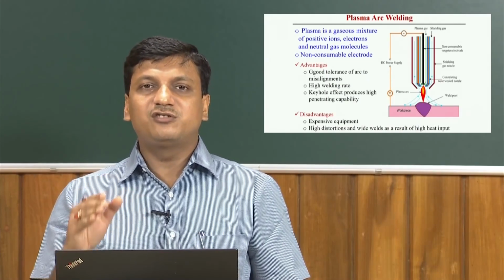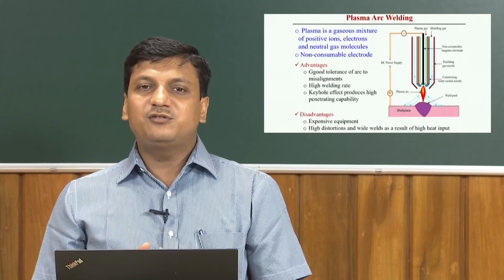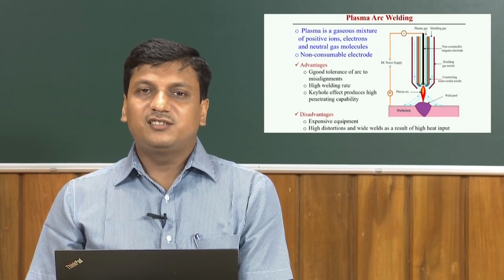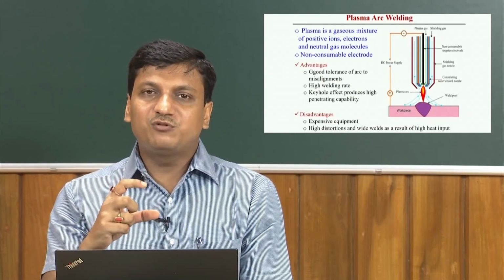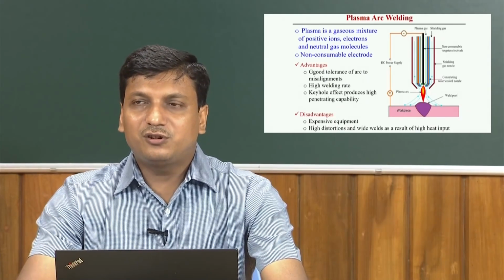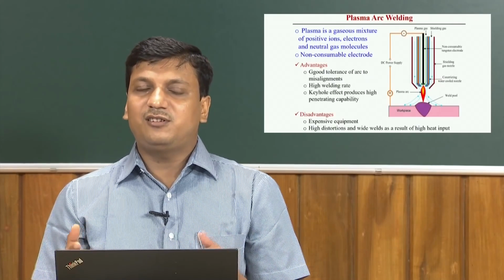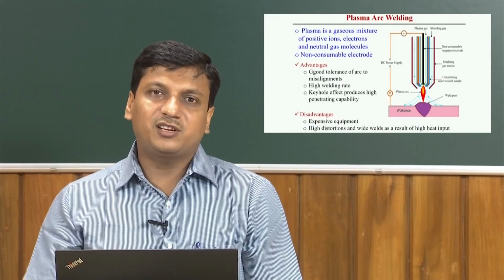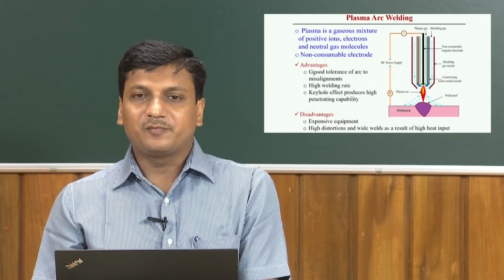That means they use a non-consumable electrode and create the electrical circuit, but here we can use another extra shielding gas, called the plasma gas, which actually creates and maintains the arc, and helps to melt the workpiece material. So, with respect to the gas tungsten arc welding process and all its general components, here there is the addition of the extra plasma shielding gas.